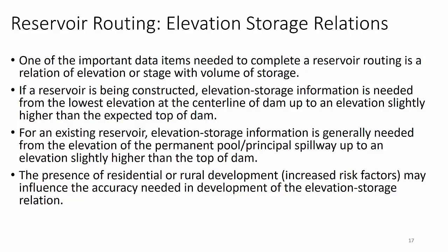So in reservoir routing, elevation-storage relationships are one of the most important processes we engage in when we design reservoirs. So you need an elevation or stage with volume of storage curve. For reservoirs being constructed, elevation-stage information is needed from the lowest elevation of the center line of the dam up to an elevation slightly higher than the expected top of the dam. And that's just a function of the geometry of the land above the reservoir or the dam that's being built.